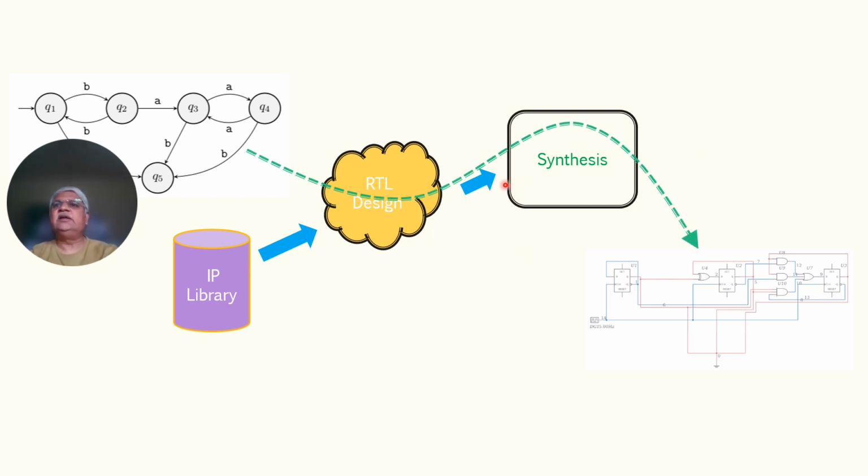So this RTL design, which is in the behavioral model, is converted through synthesis to the gate level design. This is the main way by which RTL design is converted into gate level design. There are registers here, here and here. There are combinatorial circuits here. All these things are now part of the design.